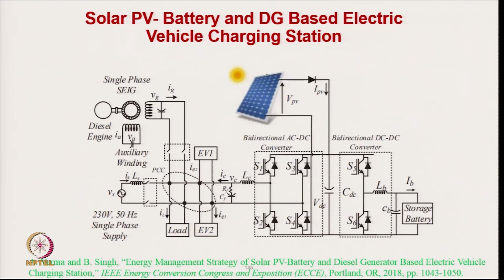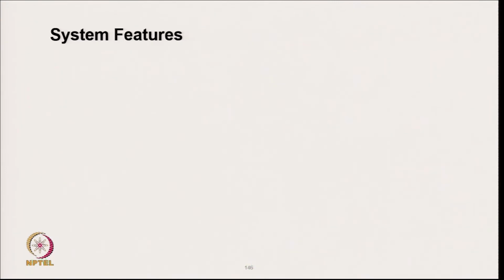This is another single phase charging station, with the concept that you should be able to charge a large number of e-rickshaws or 2-wheelers. So, we have a very large storage battery, and we have solar generation which we are charging into the battery. We have a grid if it is there, and we have a DG set if it is required. So, you have several EVs as well as a local load. So, it becomes a good, interesting charging station with a microgrid structure, providing local supply also.